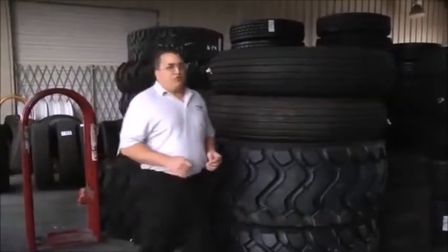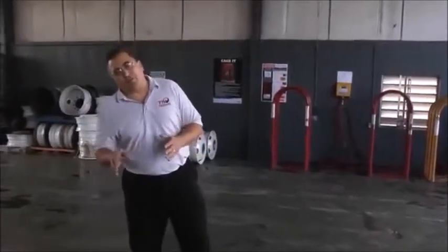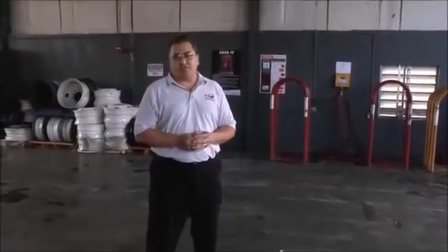When I'm doing a walkthrough inspection, I'm always going to pay special attention to the basic hazard categories, as well as any sources of motion that may put a technician at risk. I'm going to give special consideration to the proper personal protective equipment that's needed for every job in the shop. Finally, I'm going to locate the area where the restraining devices are located to inflate tires. Make sure technicians can stay outside the trajectory throughout the inflation process.